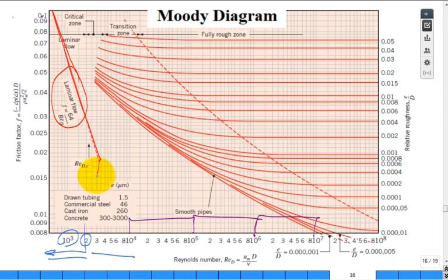The laminar flow, f is 64 over Reynolds number. We developed that for the friction factor. Guess what? You put it on a log-log plot, it's a straight line. You put it on a linear log plot, it is not a straight line. Everybody plots a Moody diagram on a log-log plot. And it's nice and easy to see, boom, straight line right there. What's the slope? -1.